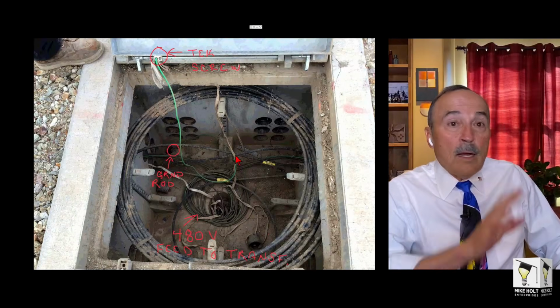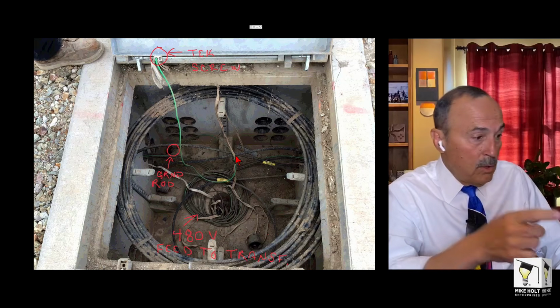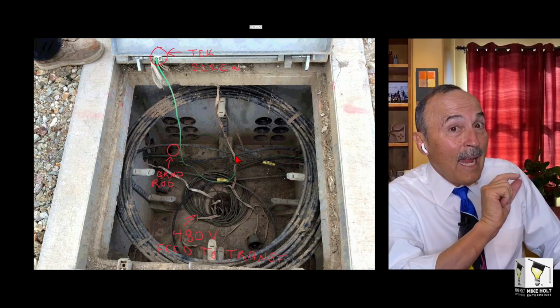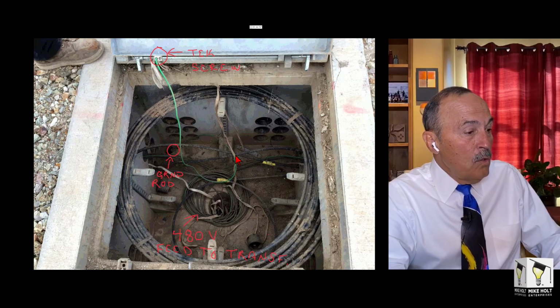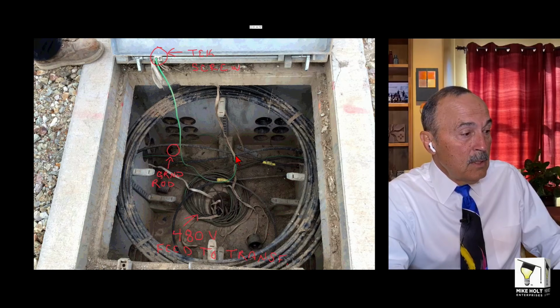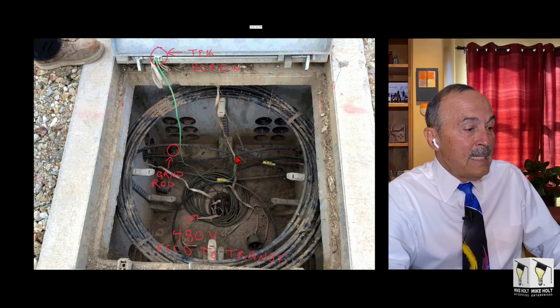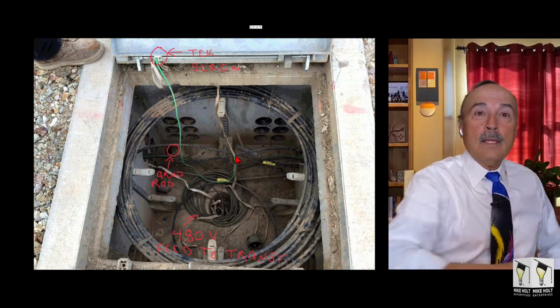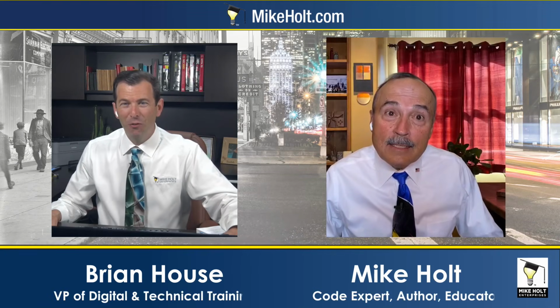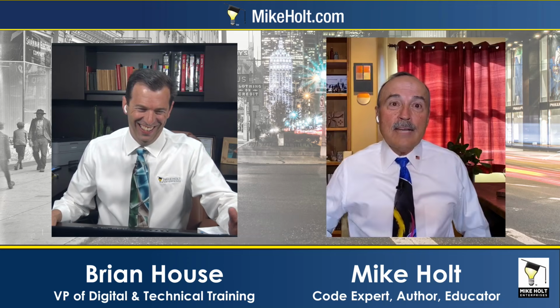Okay. The definition of a handhold enclosure in 314.30 deals with handhold enclosures. Listen to the word handhold. Handhold: an enclosure for use in underground systems provided with an open or closed bottom and sized to allow personnel to reach into but not enter. There you go. Is that the Holt version of a mic drop? Exactly. Just slam that sucker right down.